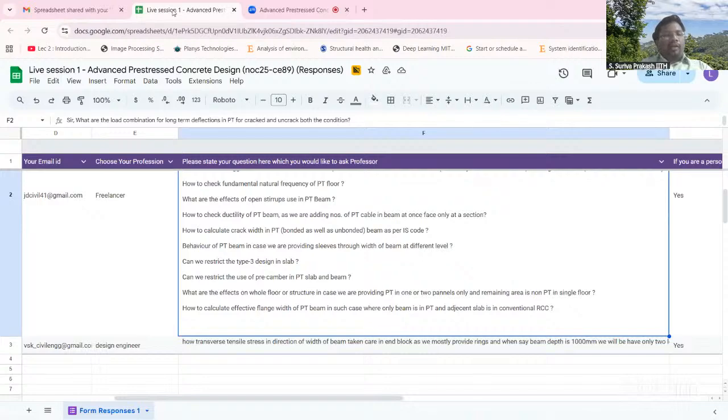So type 3 is only for very special cases. If you're a good design engineer, you have to make sure that you put enough pre-stressing so that it's not going to crack. In fact, I would say type 3 design should not be encouraged, because then you lose all the benefits of pre-stressing, right? But only for some applications that are not very critical, for an interior element, let's say, to economize the design, maybe we can go for type 3.